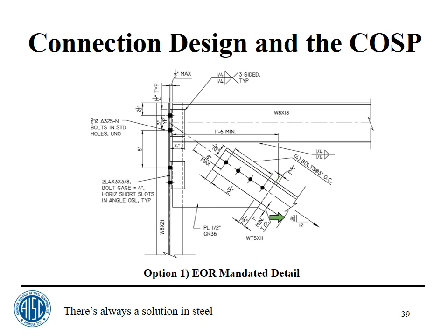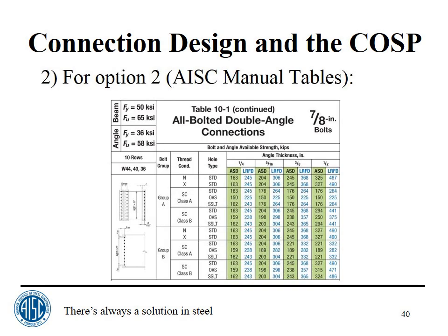The bevel's given, either the bevel or an angle. The fillet weld over here, 1/4 inch both sides. The length of the fillet is 1 foot 6. Everything is spelled out. The weld here, 3-sided, 1/4. That means top, vertical, and bottom. And since it's typical, that covers the one on the bottom. Since the angles presumably are the same, they're what, 4 by 3 by 3/8. That would be a typical engineer-mandated connection.